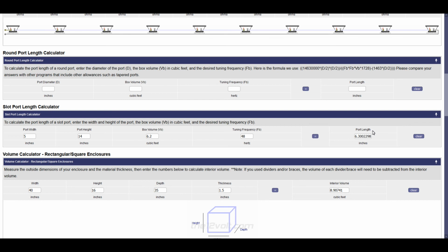But if you look at the other video with subwoofer box tuning to identify it just by playing test tones, you'll see that this plays a really key role with identifying how close it really is. So you're not going to be dead on within a hertz, but you'll be within 3 to 5 hertz for sure. That's your variance, 3 to 5 hertz max. It just depends on the box, the build, and the cabin space.